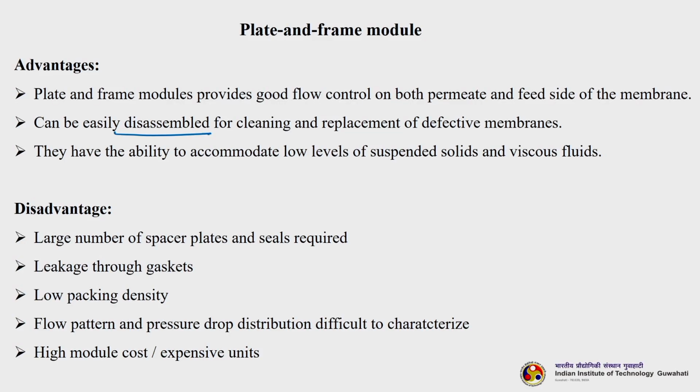However, they have many disadvantages also. The first and foremost disadvantage is that a large number of spacer plates and seals are required. So, we are complicating the flow design, basically the flow path, and there is leakage through the gaskets. There are so many gaskets utilized in this type of membrane module.